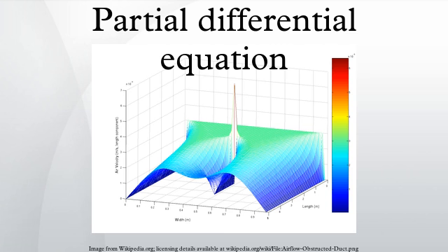Spherical waves are waves whose amplitude depends only upon the radial distance from a central point source. For such waves, the three-dimensional wave equation takes the form. This is equivalent to, and hence the quantity ρ satisfies the one-dimensional wave equation. Therefore a general solution for spherical waves has the form where f and g are completely arbitrary functions. Radiation from an antenna corresponds to the case where g is identically 0. Thus the waveform transmitted from an antenna has no distortion in time, the only distorting factor is 1 over r.